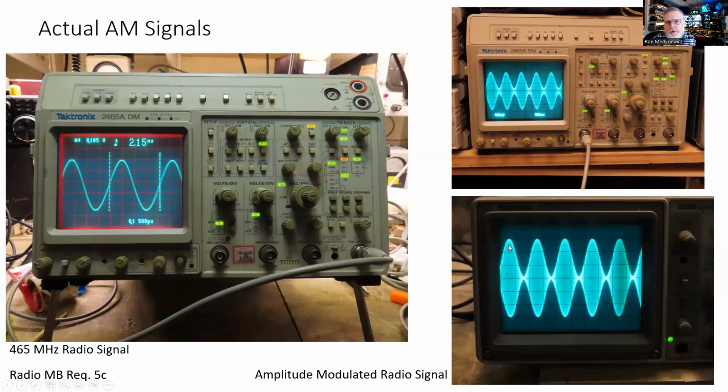Let's go down here, it's better. Inside this envelope, this is all filled with 1 megahertz in here, but we're varying that 1 megahertz at a very low, like 1,000 cycle rate in this particular case with a tone. So this is what's known as amplitude modulation, where we're taking a high frequency carrier and we are varying it at a very low frequency.